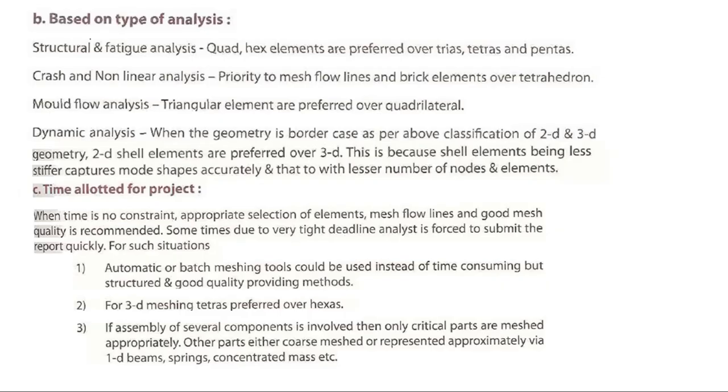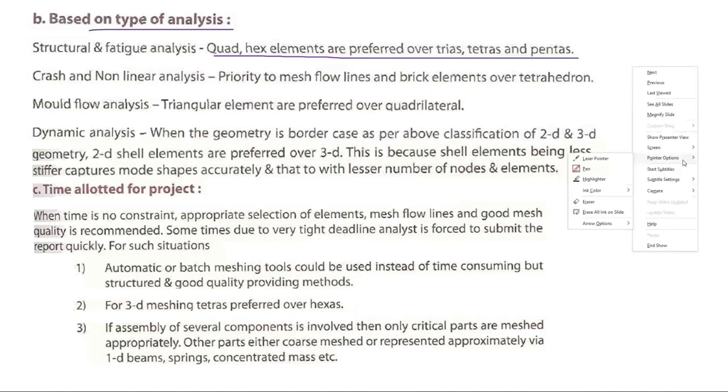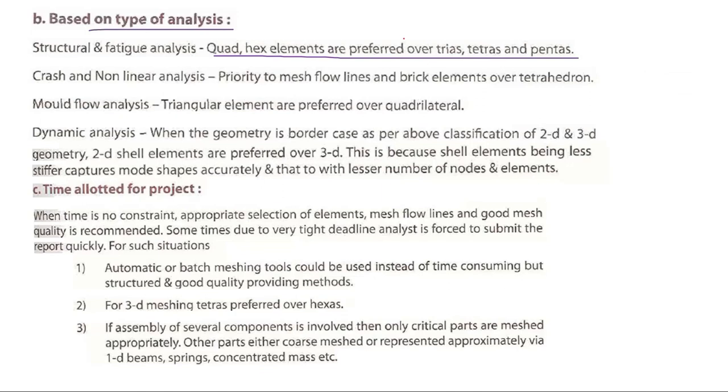Based on type of analysis: structural and fatigue analysis use quad and hex elements, which are preferred over trias, tetras, pentas. So you know, we are also going to do fatigue analysis. In that kind of analysis we use quad and hex; we prefer them compared to trias, tetras, pentas.